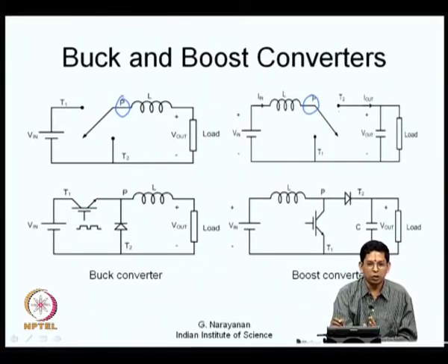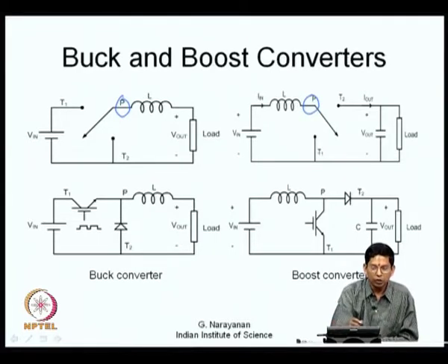A good part of power electronics is actually understanding switches and understanding how to connect switches and how not to connect switches to realize your power conversion. So, what we have been trying to do from this particular point of time is realize this single pole double throw switch. How are we trying to realize it? Pole to throw T1 and pole to throw T2. We are looking at the two states, and we are looking at the conduction and blocking requirements between P and T1 and between P and T2. The same story here, and we are realizing whatever switches are necessary.